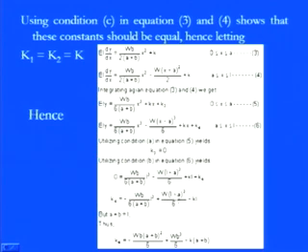So here we can simply keep this B, and we have k4 equals minus WB divided by 6 into (A plus B) whole square, because L is nothing but A plus B. So it will be cutting out those things, plus W into this (L minus A). So L minus A will be coming as B square. So you see here the B cube divided by 6 minus k times (A plus B).